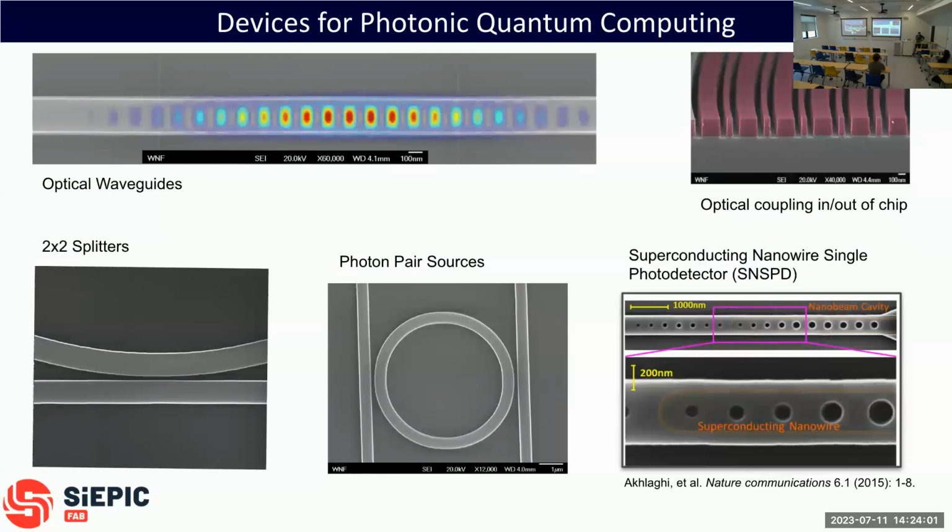Okay, so a little bit of pictures. I guess these are all UBC pictures of the types of things that we do. This is a kind of beam splitter. I did mention that you can split the light in half, so this is physically what it looks like. And you can see there's no contact. You can think of it as capacitive coupling, but it's really just the evanescent field leaking from one waveguide to another. You remember how I mentioned there's 10% of the light on the outside of the waveguide. That 10% on the outside will actually get sucked into the other waveguide.